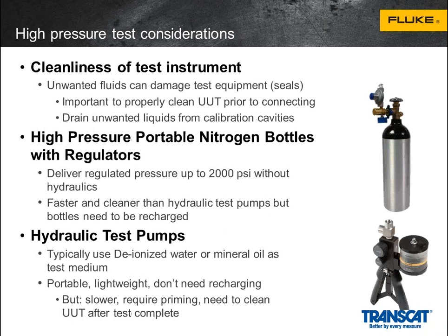So let's talk a little bit about high pressure test considerations. One of the things that a lot of technicians we see in the field struggle with is keeping their units sufficiently clean. It's very easy to damage the seals. Manufacturers try to make them as rugged as they can, but a lot of times technicians will use process pressure or flow pressure in order to pressurize the units because they don't really want to do the pumping, because, you know, the pumping's no fun. But it's easy to contaminate your unit.